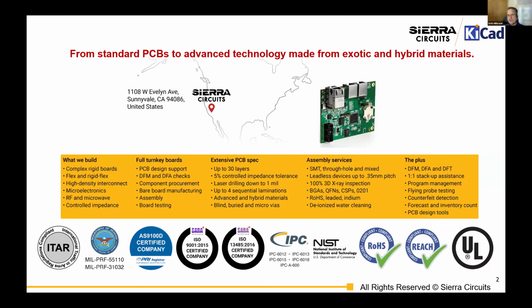Because it's not plated on the inside, there is limited solder wicking that happens, and you generally don't end up in that case with an underplated pad. Now it's not to say that it couldn't happen, and I know you're definitely the expert on fabrication processes here, but this was chosen as an example because it was one of the strangest requests that we had seen in terms of, can we do this?